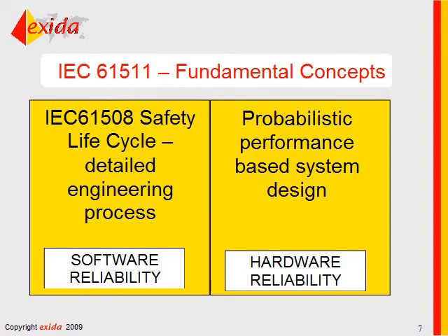So when we talk about the IEC 61511 standard, and that's going to be our focus today, there are two fundamental concepts. One is a safety life cycle that basically prescribes a detailed engineering process, and the other is a probabilistic performance-based system design. The life cycle approach makes sure that you go through a very rigorous process, that you cross your T's, dot your I's, and